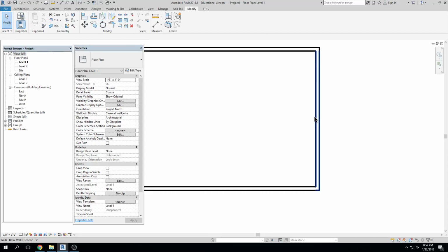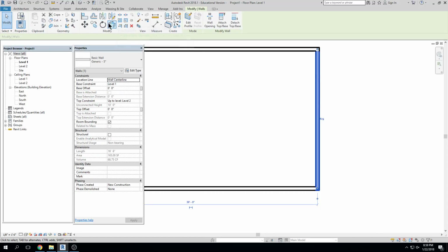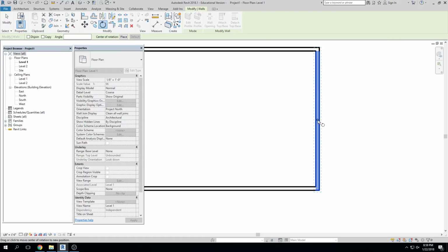All right, so let's click this again. I'm going to click on rotate, right? Or I could type RO. I can grab this little grip. I'm clicked on it and I'm holding my mouse button down. I'm going to drag this down to here, let go, and now my base point has been established at that bottom corner. Click. Let's say I want to go this direction, right? I get the positive, negative nature of AutoCAD because it's meant for architects, engineers, it's meant for everybody, right?